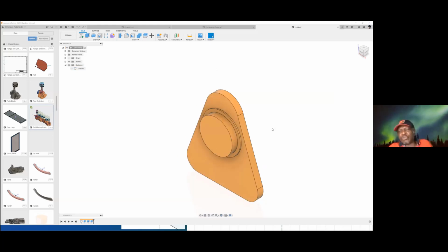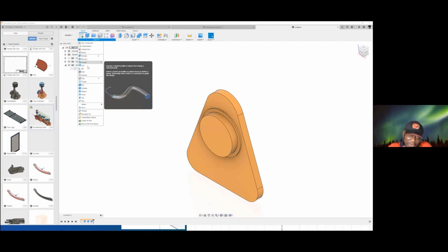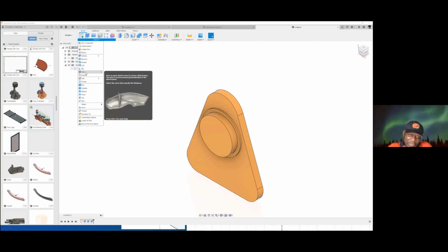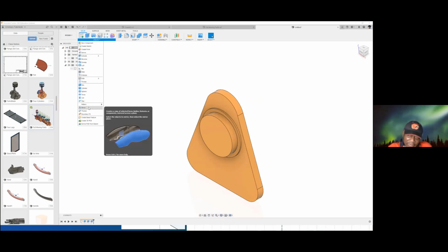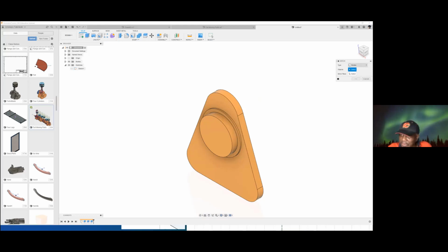So what I'm going to do now is to mirror this to get the leg of the crankshaft. If I mirror this whole thing, I just say create mirror. This is a 3-dimensional mirror, unlike the 2-dimensional mirror that needed a line. When you create a mirror like this, you will need a plane. So create mirror, and you are creating a mirror of bodies. Everything here is a single body. And then it says mirror plane. You now want to select the mirror plane.